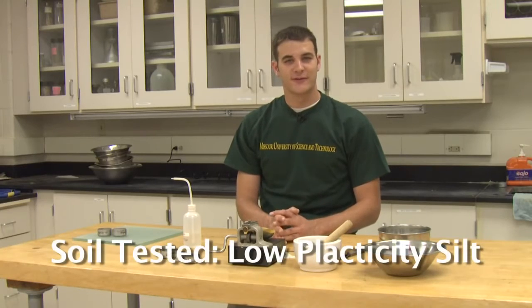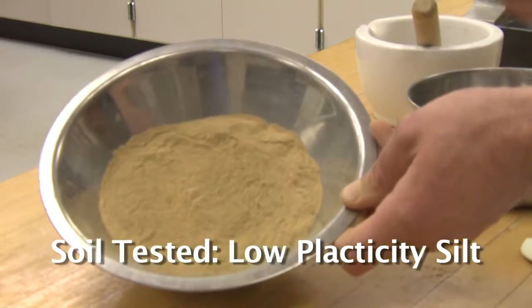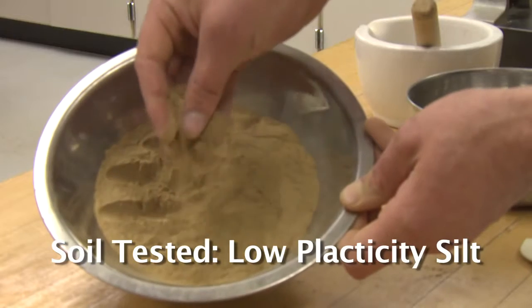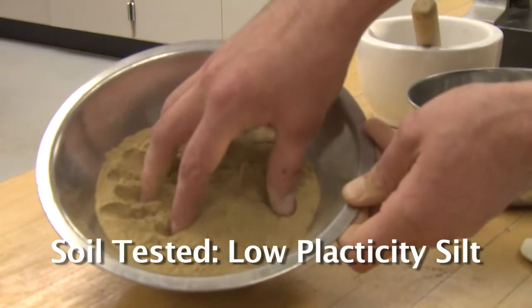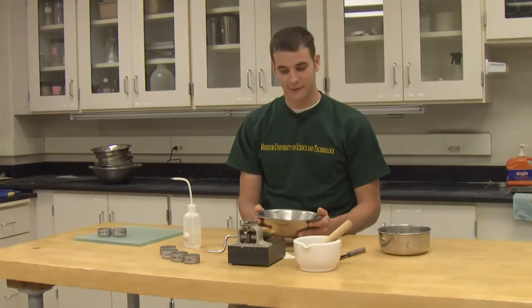This short video will demonstrate how to conduct a liquid limit test and a plastic limit test in accordance with ASTM specifications. The soil that we will be performing the limits test with today is a loessial silt that comes from the Mississippi River Valley. This silt has been mechanically pulverized and then passed through a number 40 sieve to remove all large particles. For the purpose of today's lab experiment, bentonite clay has been added to increase the plasticity of the soil.